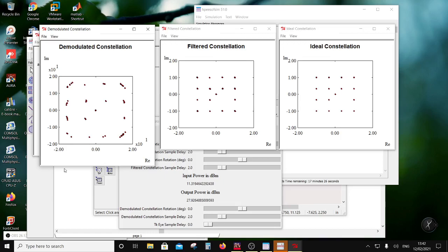Still the power is not built up because one symbol is missing. The average power is going to be 28.6. Okay, so you understood why this constellation is disturbed. That's the phase noise of the PLL. One symbol is missing, persistence.